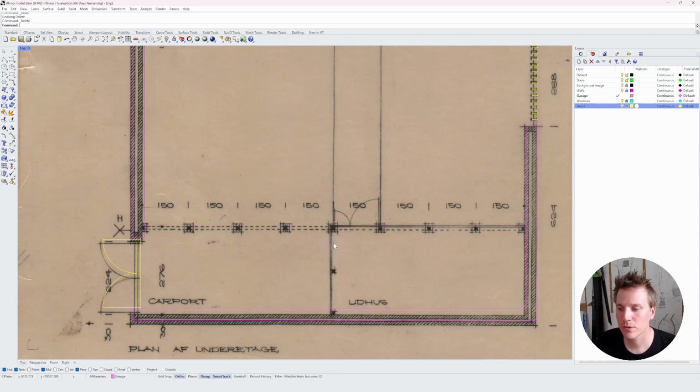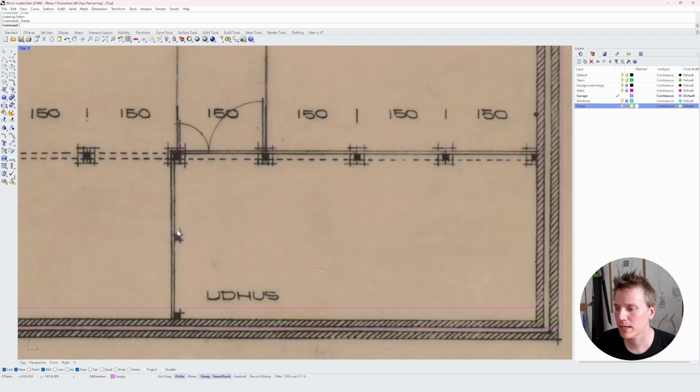Now let's just quickly draw the wall around and these small doors here. So we can see that we actually need 2 more columns. I'm going to copy one of them and make it hit the wall down here. And then to cheat a little bit, I'm going to make a line here. And then I'm going to copy one of them from the midpoint to this midpoint that's exactly halfway between these two. And now you can see this line goes all the way around.